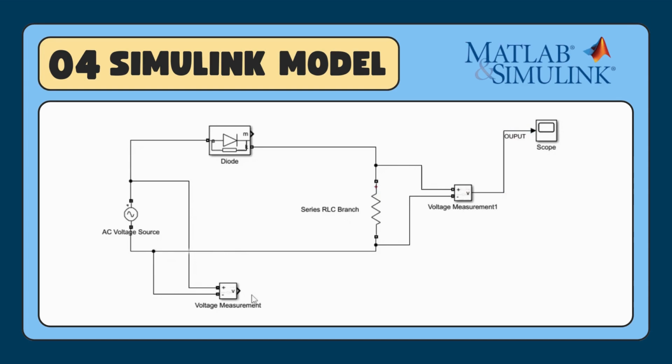Next, we have the diode, or the rectifying element. The diode is the most important block in this model. Its function is to allow current to flow in one direction. When the input voltage is positive, the diode is forward biased and conducts. When the input voltage becomes negative, the diode is reverse biased and blocks the current.